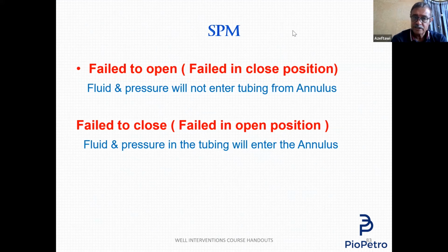I have a question actually, which is a nice question. I have two questions. To do its circulation function and communication between an annulus and tubing, it should be positioned just above the packer. We said no, one joint above the packer. You mentioned we use wireline to jar up and jar down to get the SSD open. I was wondering if it is the same for highly deviated wells. This is a good question. Because he said, Ahmed, use jar up or jar down, but what about high deviated wells?